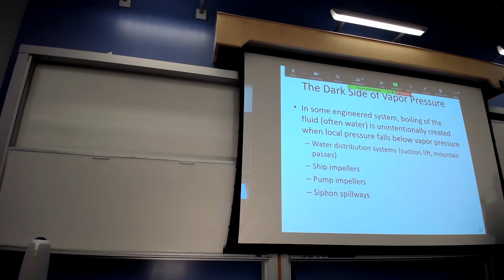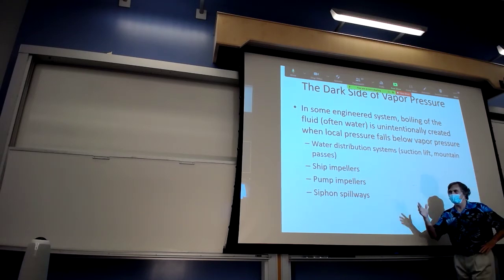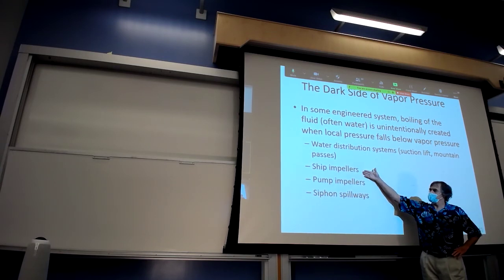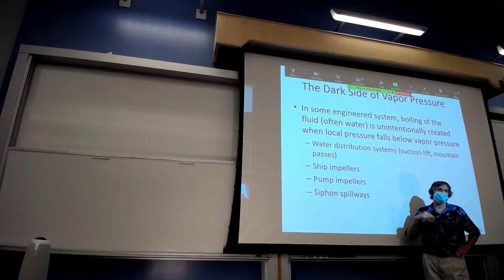If you get air building up in these systems because you volatilize the water, you can have the water completely stop, or you can dramatically increase pressures, dramatically increase energy losses. So the other place, and I'll show you a picture, which is actually a video, you'll see it in ship impellers, pump impellers, siphon spillways.